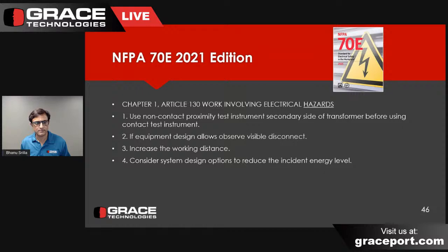But like I said, industry stopped at 40 a decade ago, and it was wrong. It was miscommunicated to you. I encourage you to look at arc flash suits at 75, 100, 140 cals.